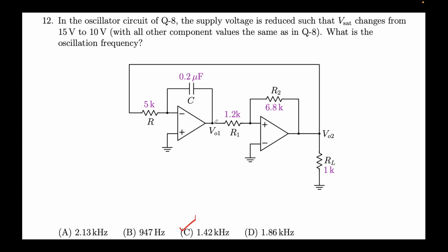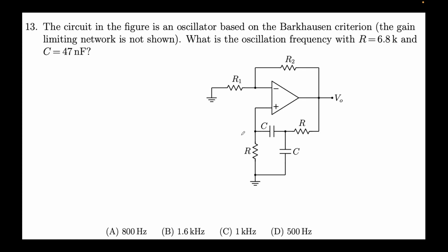And you can see that we can change their frequencies and their slopes and many other things we have controlled just by controlling RC, R1 and R2. Okay, so this is a very powerful tool that Schmitt triggers provide us. It's a positive feedback circuit. Okay, another one of the core things in oscillators is that if we want a sinusoidal output, it should be sinusoidal. Okay, it should not be any other strange waveform when we are opting for sinusoidal.